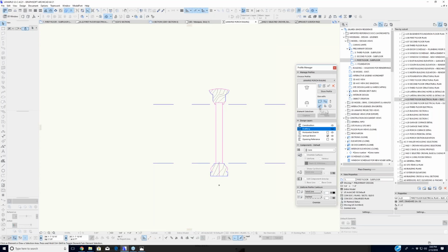Now, generally what you'd want to do is have the upper part one piece and a separate thing for the lower part, because then in the railing tool, you can say the top rail is this height and the bottom rail is that height. And of course you could mix and match, etc. But you could now do that with the railing tool. So what you've been doing manually with different pieces, you could do in something that's more of an intelligent object, run a railing around here or run a railing up the stair.